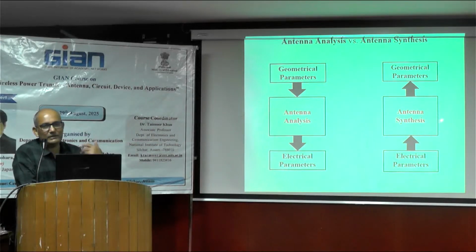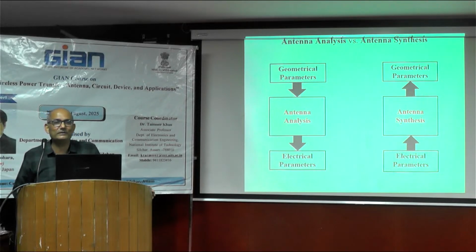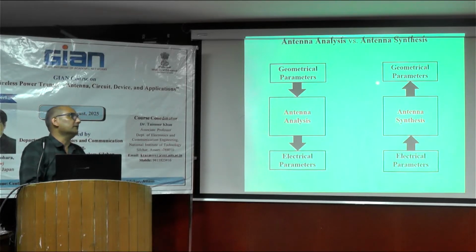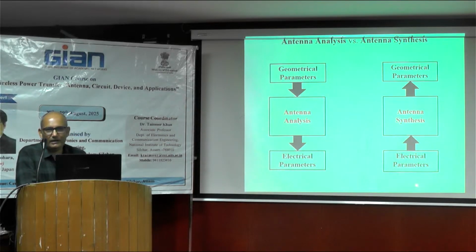Now take it in reverse. Performance is given to you: I need to design an antenna with certain bandwidth, a certain amount of gain, and you need to derive the geometry of that one. That will come under the reverse way, that is antenna synthesis. You need to remember that in analysis, prediction of electrical parameters will be there for the given geometrical parameters. In case of synthesis, prediction of geometrical parameters will be there for the given electrical parameters.